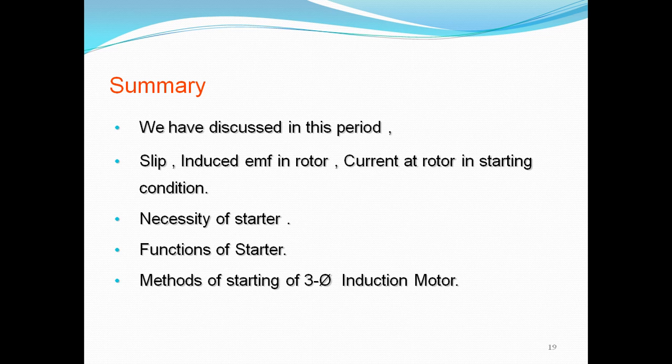The rotor resistance starter is not applicable for a squirrel cage rotor. It is applicable for a phase wound rotor only. Why? Because in a squirrel cage rotor, it is not possible to add any external resistance in series with the rotor, because the rotor windings are short circuited by the end rings.